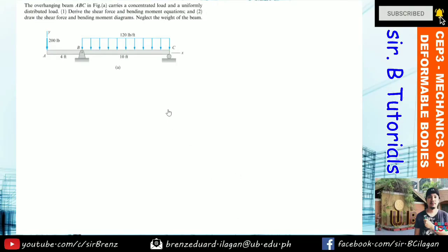Okay guys, so ito yung second problem natin. So again, this is a overhang beam. So just like the previous example, we need to solve first for the value of the reaction. So again, let's name this as BY. This one as CY. So again, moment ka lang sa isang point para makuha mo yung isang reaction. So para mas madali, moment lang tayo sa C in order to solve for BY.